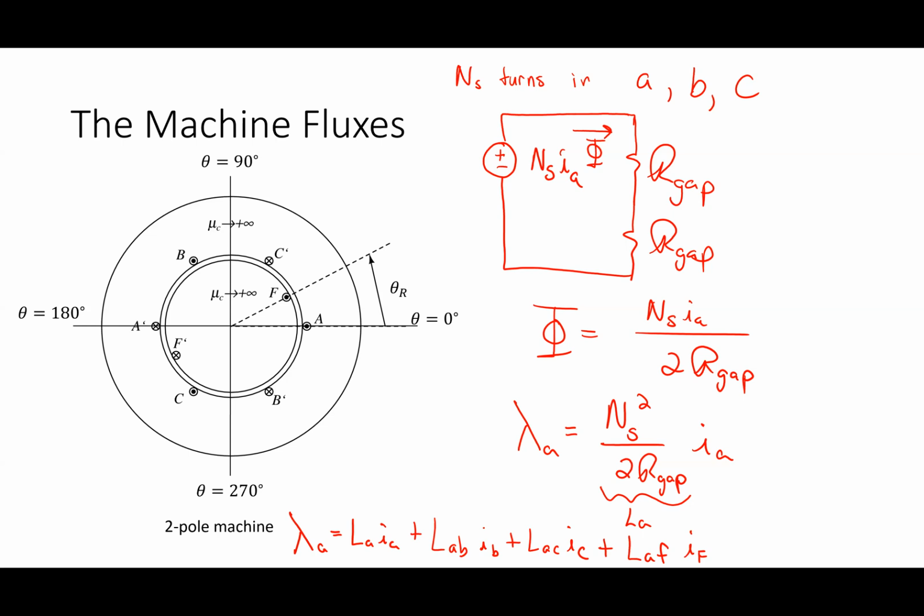All depends. We're not going to rule anything out yet. So there's a step from this, right? If I look at this equation here, it tells me lambda A equals LAIA. That's what I get from my magnetic circuits. If I want to jump to an electrical circuit model, you guys know this is an inductor, right? If I have an inductor and we use the passive sign convention, you would say this is VA, IA goes into the plus sign.